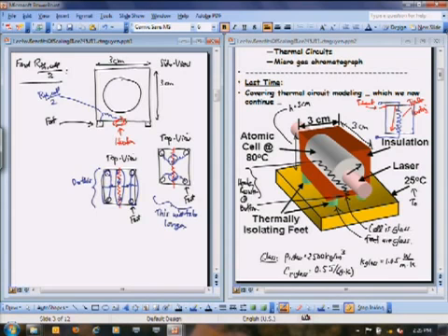Did you have a question? Yeah. Why is it the thermal resistance over 2 instead of twice? Yeah, I guess what I'm really trying to do is I'm saying that I'm doing this. Remember in the equivalent circuit from last time we had this? This is where those thermal resistances over 2 came from. Right? So it's part of our equivalent circuit. That's why I'm calling it thermal resistance over 2.